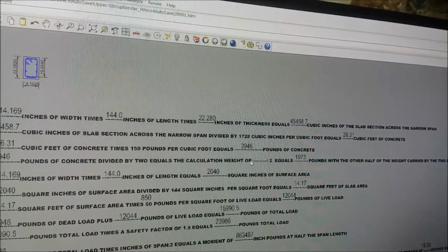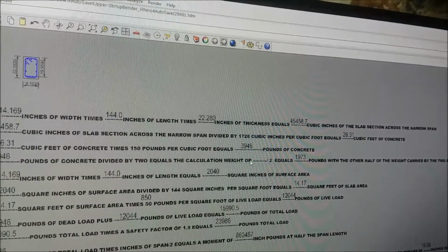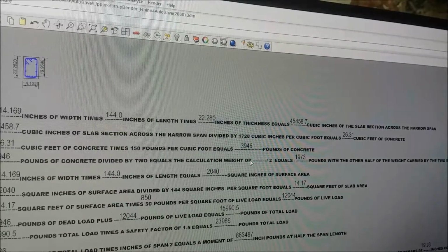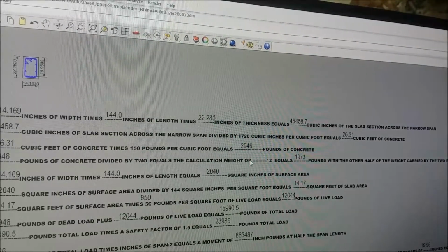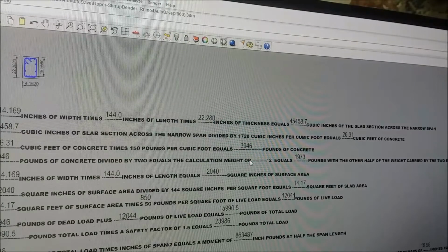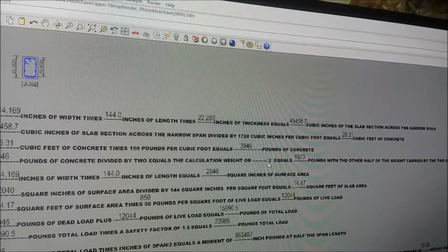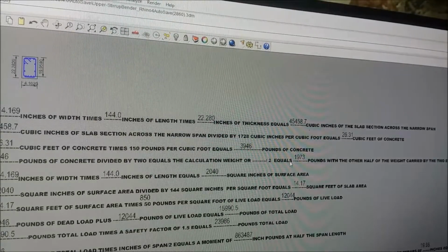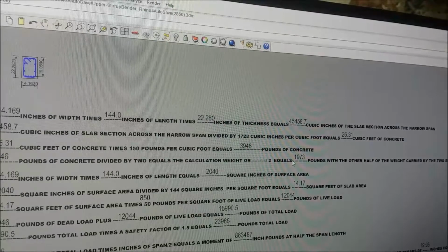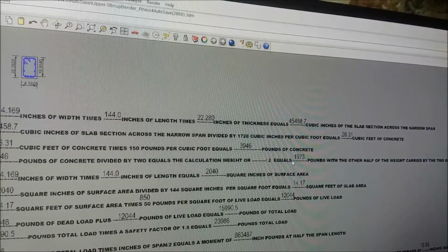That's the same as we did at the top, where half is on the ends of something. The other half is divided into basically force of the original. They add back together because you're doing them at the same point, and it makes it over 2. So it's half of the total weight. So 3,946 over 2 equals 1,973 pounds, with the other half of the weight supported on the 2 endpoints.